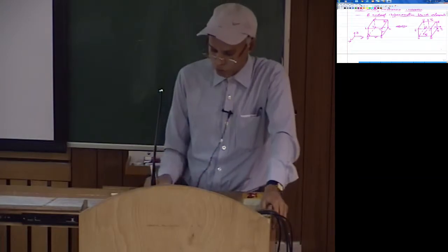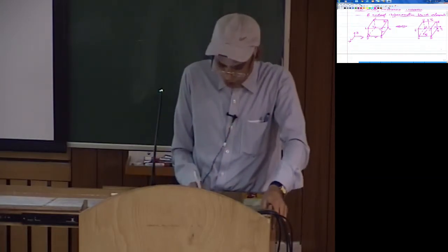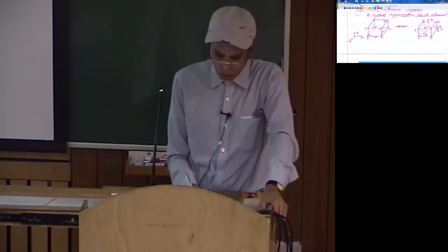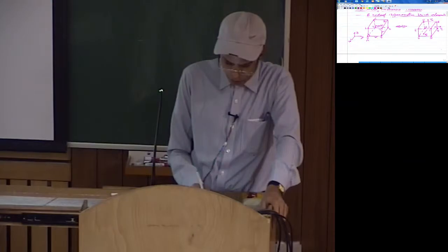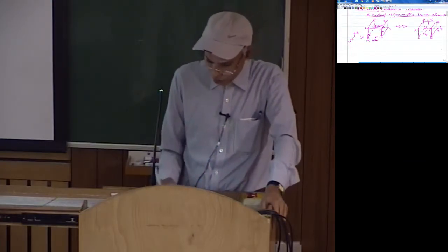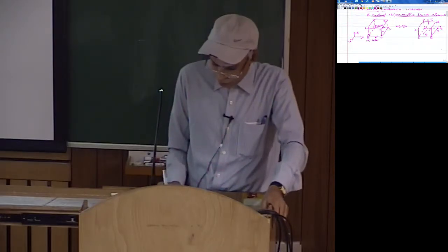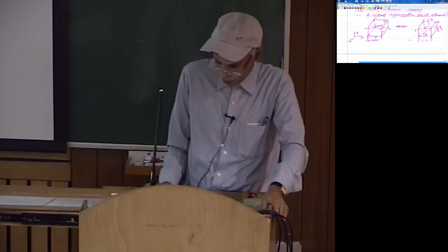If you look at the coordinates of node 1, of course the coordinates in physical space are like x1, y1, z1. For example, the coordinates here would be x2, y2, z2 and so on. In the natural coordinates, node 1 is going to be -1, -1, -1.